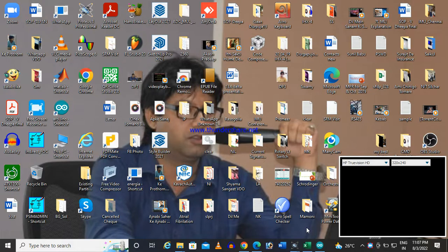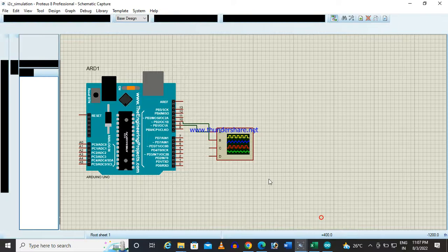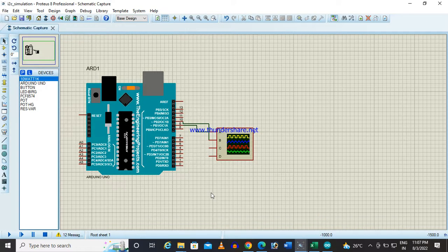So today we are going to learn how to generate high frequency PWM with a defined switching frequency. Normally we are going to learn it through the ATmega328P. You can already see my videos about PWM and sine PWM, where we define the resolution and the frequency of the PWM through the waveform generation bits which are there in the TCCRA and B registers.